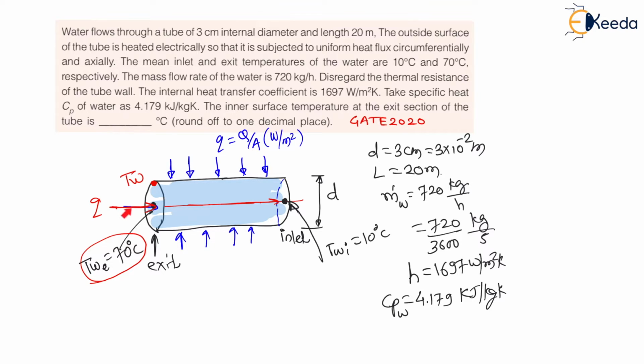Now my dear students, here heat flux along axial direction as well as along circumferential direction is same, right? Now this heat flux along circumferential direction will be by conduction, because in this wall there will be a conduction. Therefore q into, for this conduction the perpendicular area is a circumferential area, right? Therefore heat transfer, what are the modes of heat transfer? Let us observe here. Heat transfer is equal to, now along circumferential direction, this heat flux into area. Now area is circumferential along this direction. Therefore circumferential area is pi d l. This will be the heat transfer.